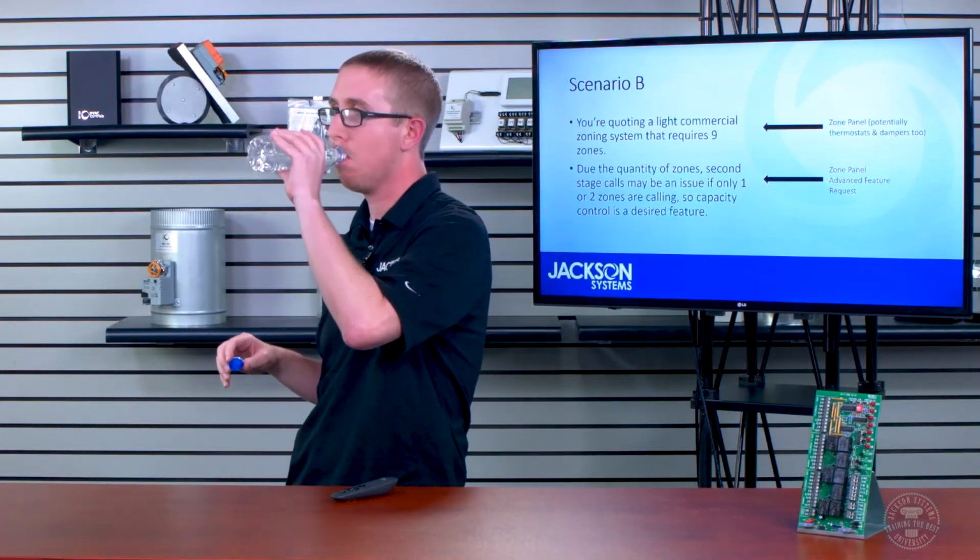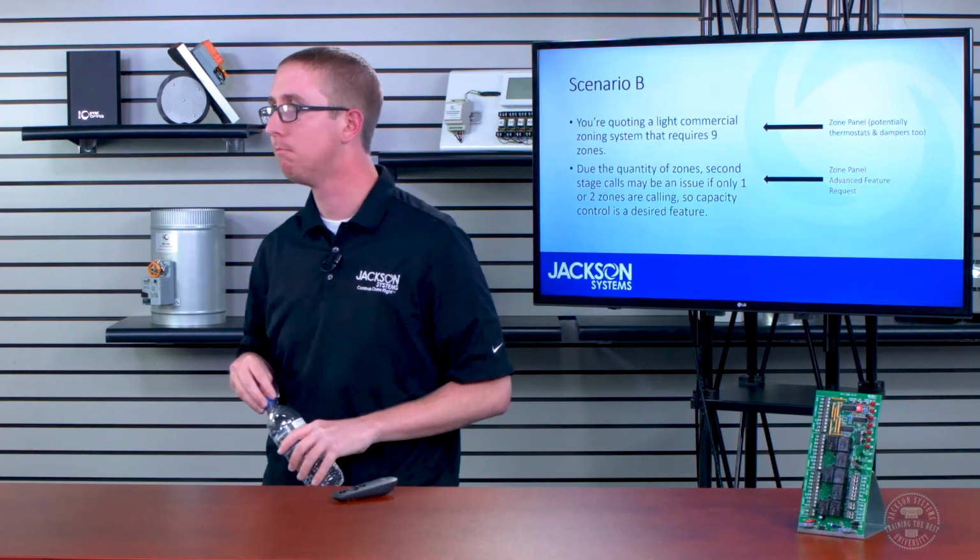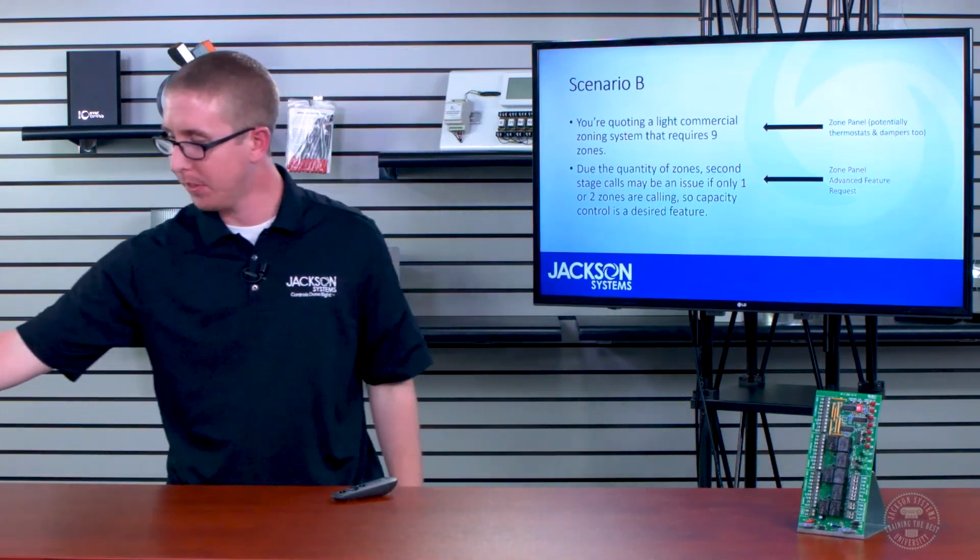This is going back to bypass dampers, and they said, what about using a dump zone? That used to be the more common method: pick a part of the house and, instead of bypassing, dump the excess air into that area of the home. While that does work, the thing we always ask is, what part of the house don't you want to be comfortable? If they had a room that never got used, that would be okay, but I would really prefer the bypass.